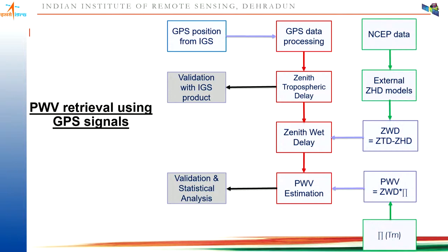They are collecting data from the various reference stations, and then they are doing orbit determination, or analyzing the orbits of the GPS satellites, and then they are posting the precise positions of the GPS satellites.